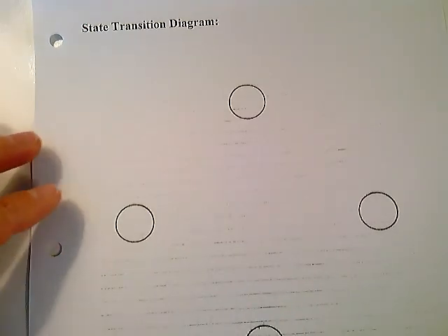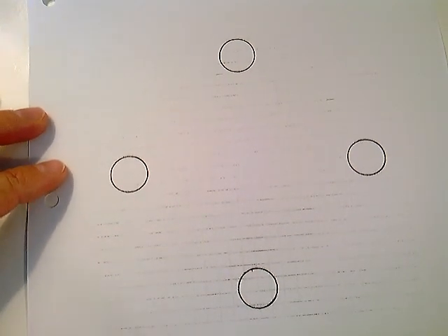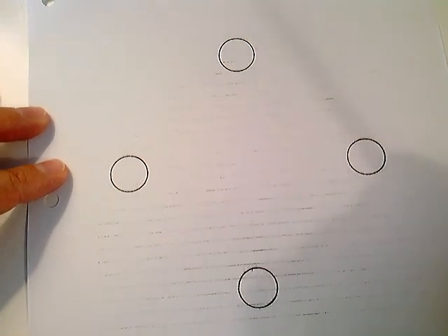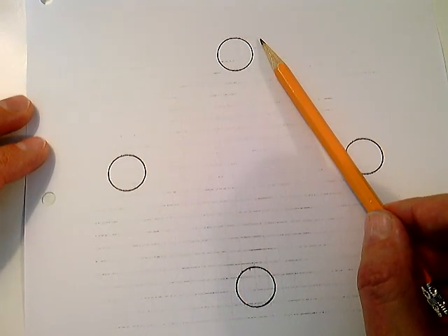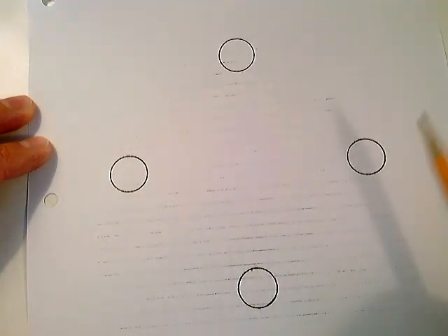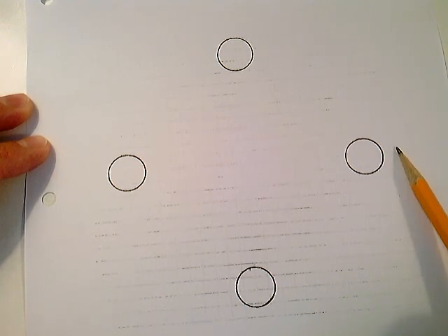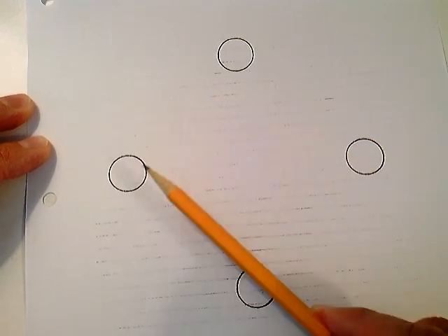So you read over the specification, and then you just come up, for me, with the state transition diagram here on page 237. That's the homework. All you have is 4 circles, so there's your 4 states. You can label these states. This state here is going to be your off state. Okay. This state here is going to be 2 states. It's going to be 1 state, but it's going to be your soak and your rinse state. This is your wash state, and this is your wax state.